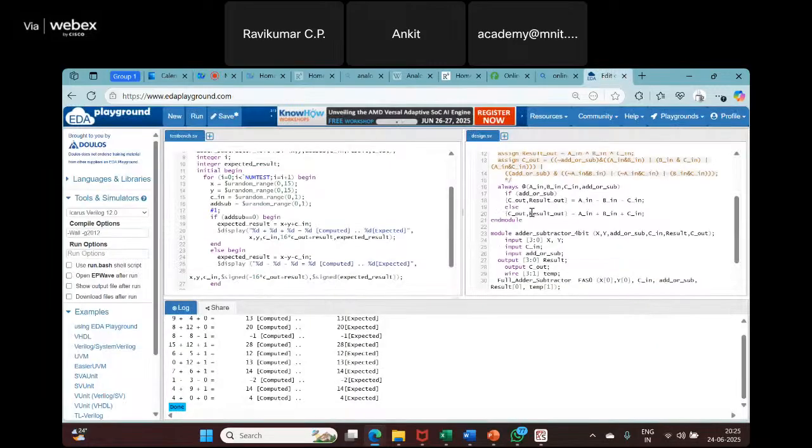They figured out that when I add 3 bits, the carry has the higher position. If you treat the sum as a 2-bit number, it should be carry out followed by result out, not the other way around. When we do things in a hurry, all these things occur, right?